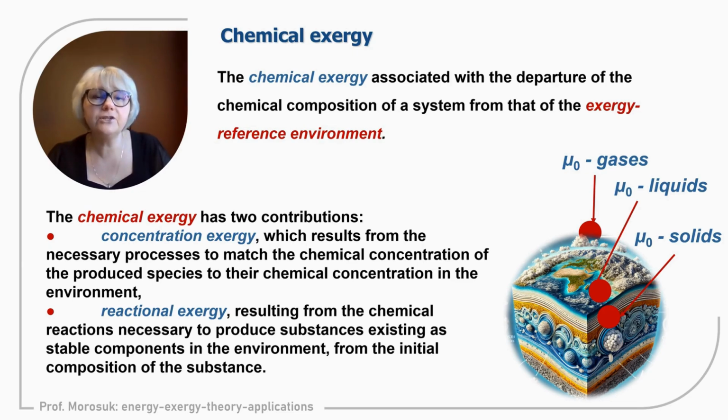And chemical exergy can be discussed as a departure of the system from the exergy reference environment, when the system and environment already have the same temperature T0 and the same pressure P0. And chemical exergy has two contributions. Therefore, we can discuss concentration exergy and we can discuss reaction exergy.